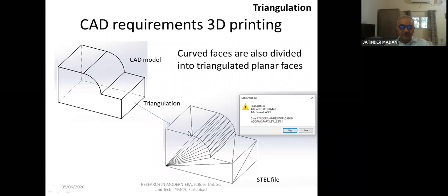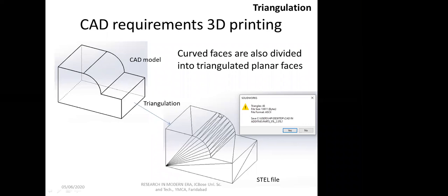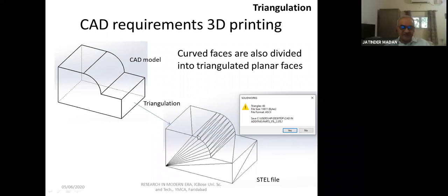Okay, so here you can see that these surfaces have been converted into a triangulated or STL file. So this surface is two triangles. Here also one big triangle and then small triangles, just to match this curvature. So you have smaller triangles to match these, smaller triangles here too, and here again big triangles. And here you can see 48 triangles. So this is a better approximation.